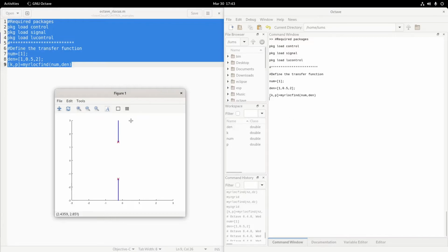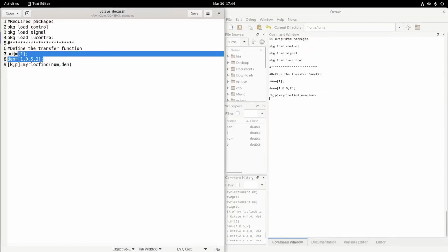So you see here that you can put in the grid. You have a figure window here. You have the pole locations. You have two complex conjugate poles here, left of the zero line, which means the poles are stable. So this is the root locus of this continuous domain transfer function as we have seen here.